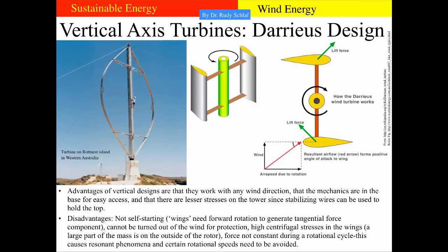The advantages of this design are that they work with any wind direction because of their rotational symmetry. The mechanics are in the base for easy access, so one doesn't have to climb a tower. And there are lesser stresses on the tower since the structure can be stabilized with wires attached to the top.